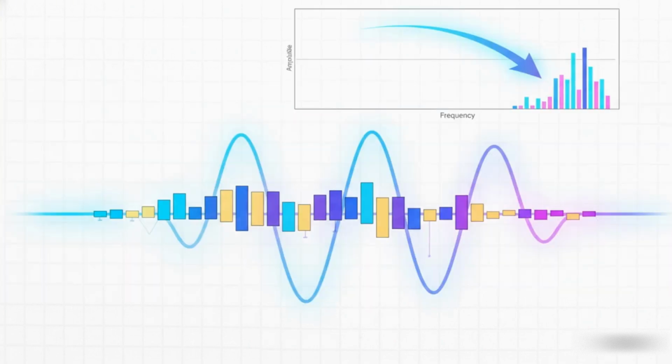And this right here is the magic of PWM. The actual voltage coming out of the inverter isn't a smooth sine wave at all. It's this high-speed train of rectangular pulses, constantly flipping between full positive and full negative. But, and this is the whole trick, because we're switching so incredibly fast, the average value of all those little pulses perfectly traces out the shape of our sine wave reference. It's like we're sculpting a perfect sine wave out of thousands of tiny digital building blocks.